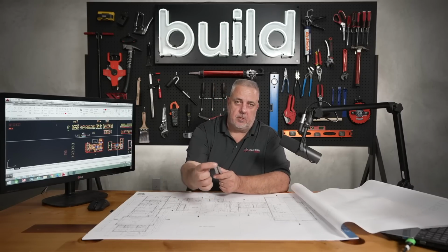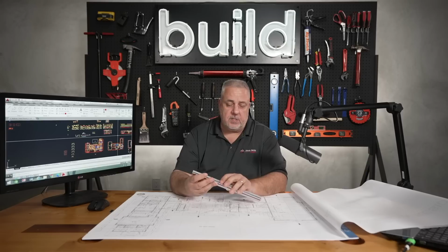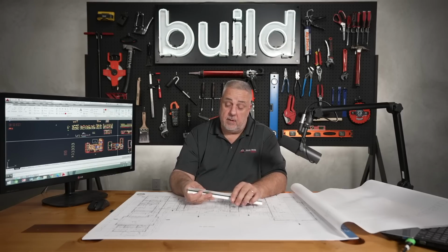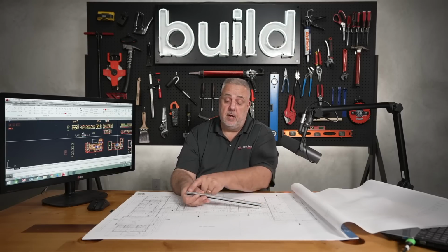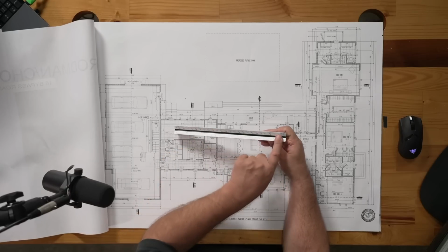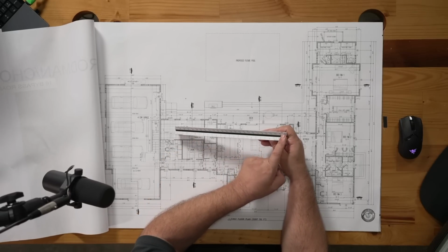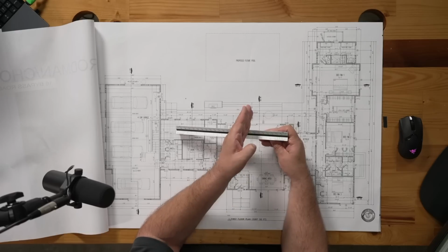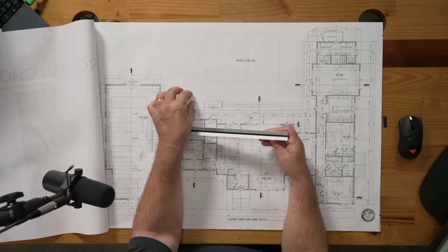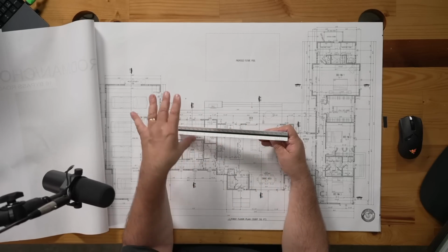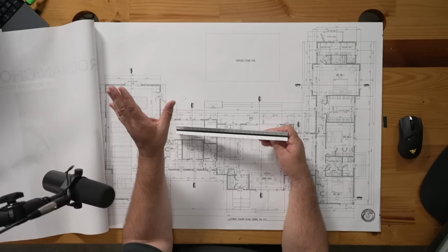Most of the time they're triangular in nature, and they have a whole series of different scales. This one here, the 1/4 inch, is down this side. It's read right to left. And basically 1/4 inch scale simply means that for every 1/4 of an inch of paper space, meaning space on the paper, it equals 1 foot of actual space.